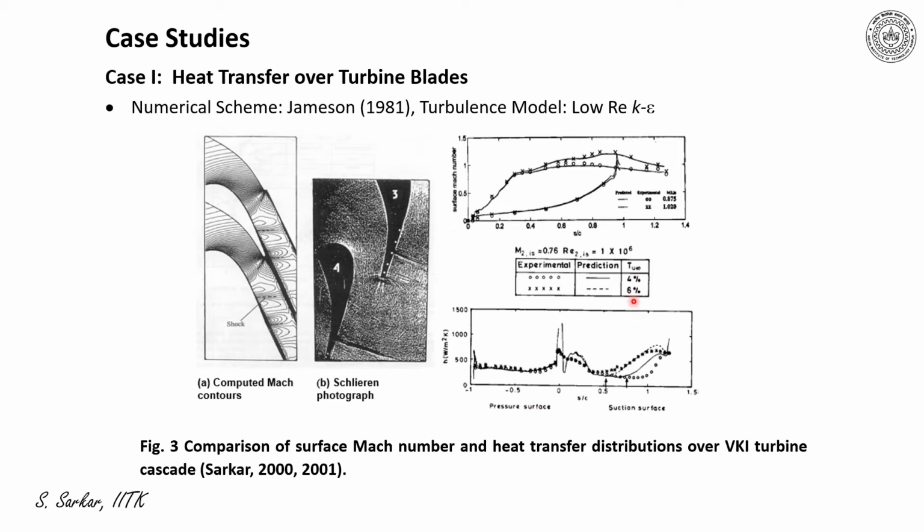Furthermore, I have evaluated heat transfer for different free stream turbulence levels. I have considered turbulence levels of 4% and 6%, and it has been seen that at 6% the prediction is very good. The onset and end of transition compare very well, illustrating the augmentation of heat transfer on the suction surface. However, at 4%, the comparison is not as good. It has predicted an early onset. On the pressure surface, the flow remains almost laminar for both free stream turbulence levels, and it compared well with the experiments.